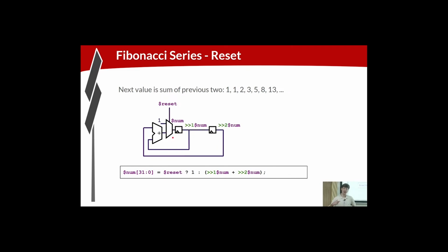And then, as I said before, we rely on the clock, which will be running during reset, to propagate that 1 forward. So after reset, we're going to have a 1 here, here, and here. Okay, importantly, we have a 1 here and a 1 here. And then we deassert reset. Those 1s get added and become a 2, and the circuit continues.